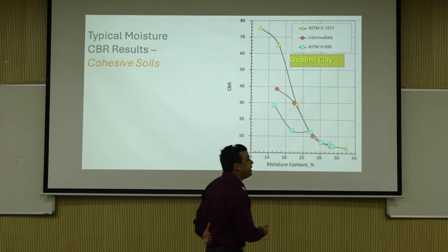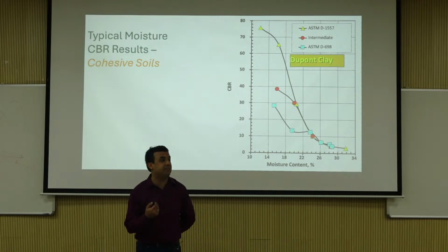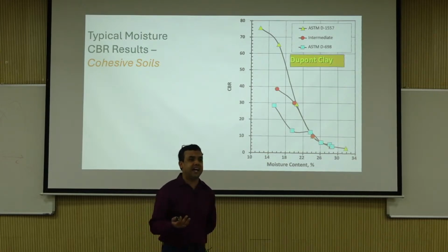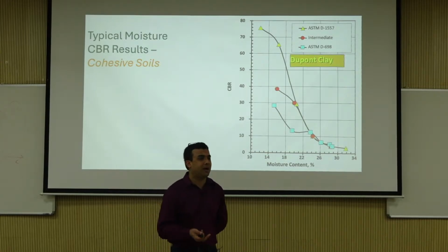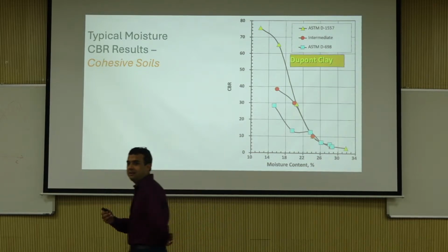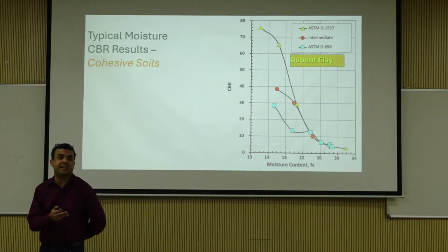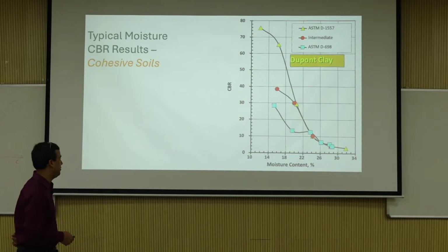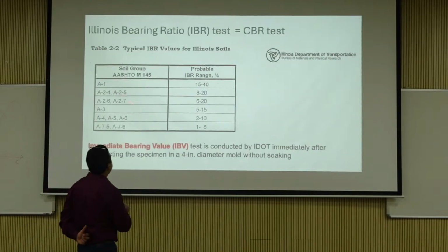But what is the point of soaking an aggregate if it is a very low fines aggregate? Because what happens to the water? It just drains, right? So your water does not really change the behavior as much unless you have plastic fines. So that's basically soil groups.